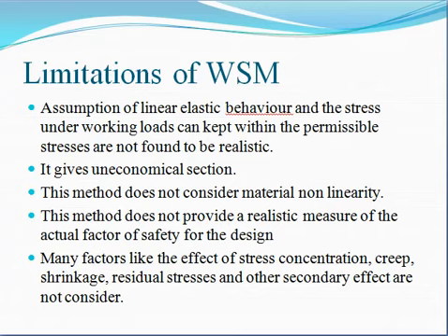The first limitation is the assumption of linear elastic behavior, and that the stress under the working loads can be kept within the permissible stresses, are not found to be realistic. While designing the structure by using the working stress method, we assume that the material is linear elastic, means the behavior of the material is linear elastic. But in practice, in real life, it is not possible. So this is the limitation of the working stress method.